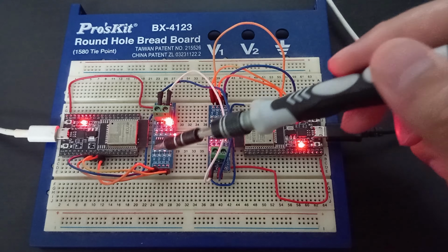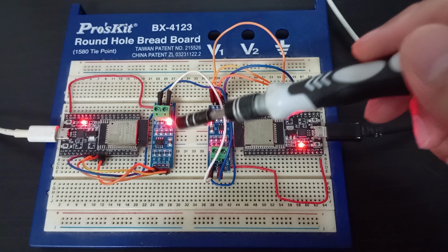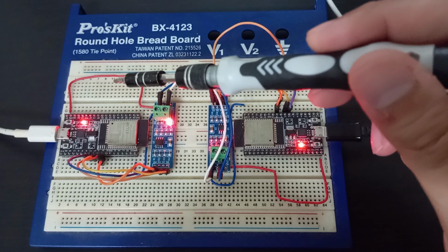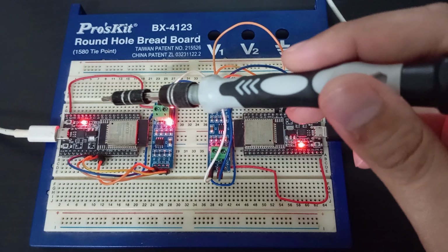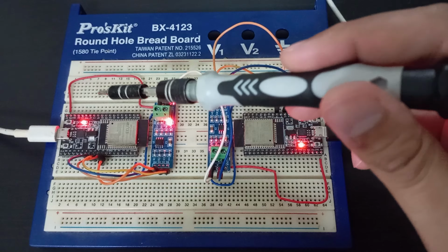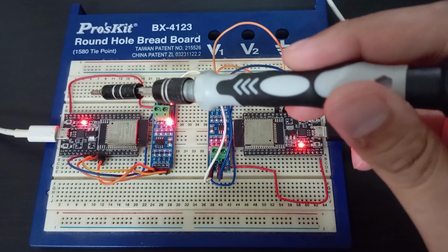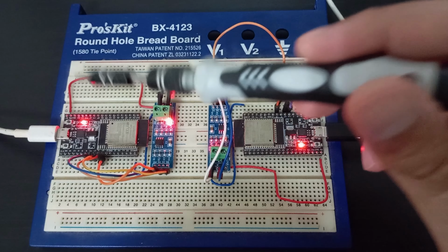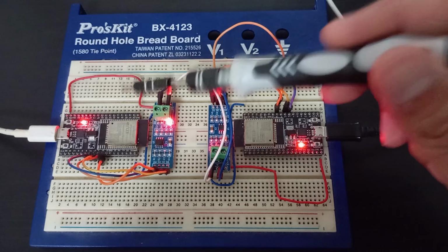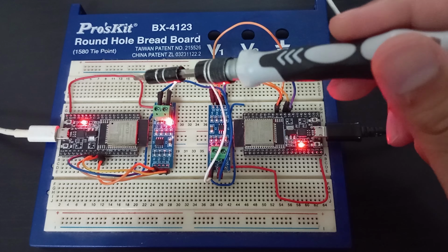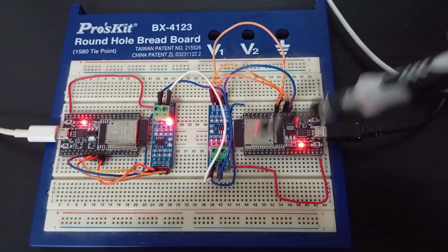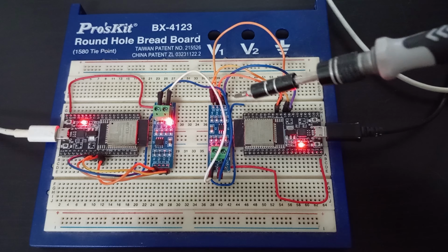Then we have RO and DI, which are basically the TX and RX, involved with the ESP32. So the RS-485 TX pin from the ESP32 will be pin 17, and the RX pin will be 16. The DE and RE pins will both be connected to pin 18. Everything is on UART num 1, okay? A and B are connected to A and B as well, and the connection here is the same.